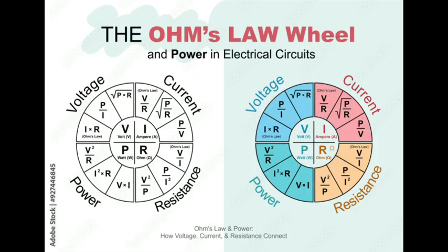They're all receiving the same amount of pressure, so all of them will be bright. They're receiving the full potential of the circuit. They're giving very little resistance to the flow of current, so our lights are actually very, very bright. And this is the same thing as our drawing that we have up there. And by knowing this, I could figure out how many amps are flowing through that light using Ohm's law. So what would be the total amperage, the total power, and the total resistance of the circuit? Go ahead and solve it using Ohm's law.